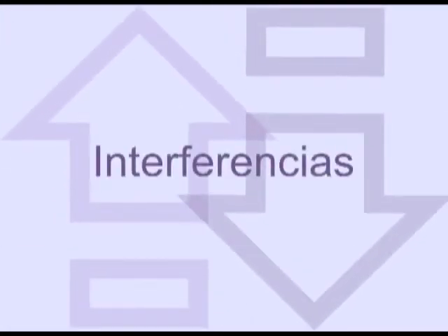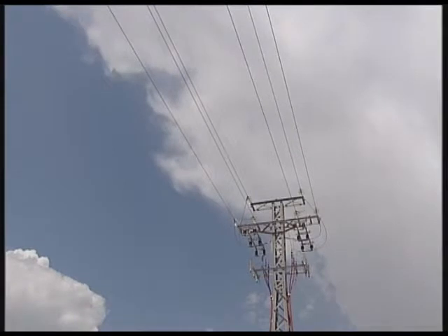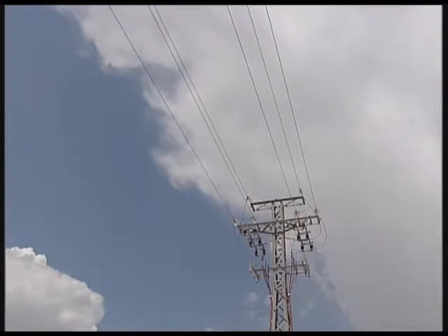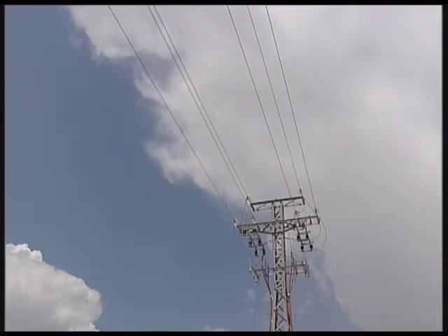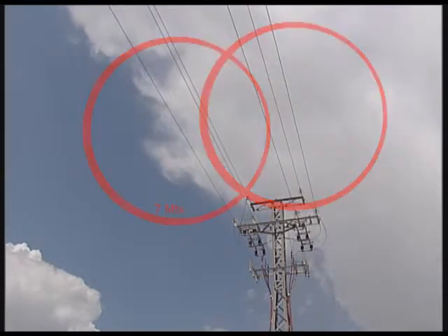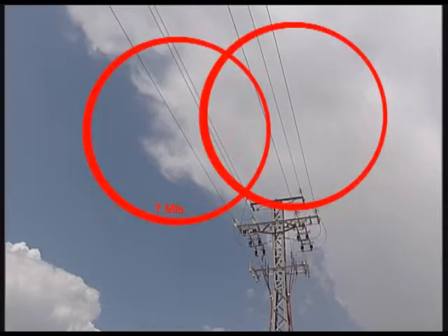Danger zones. The usual danger zones are electrical high voltage lines. The nearest a crane can be to a high tension cable is 5 meters if the voltage is not greater than 380,000 volts, and 7 meters if the voltage is equal to or greater than 380,000 volts.